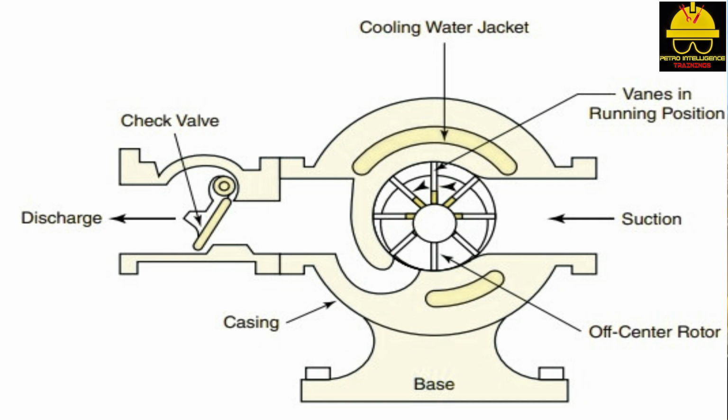As gas enters the sliding vane compressor, it is captured in vanes and swept around the casing, filling the chamber. As the vanes rotate toward the discharge, the vane length shortens because of the rotor's eccentric position with the shaft, and volume is decreased. As volume decreases, pressure increases until maximum compression is achieved. At this point, the gas is discharged out of the compressor. This type of compressor does not use suction or discharge valves because it is designed to discharge against system pressure.